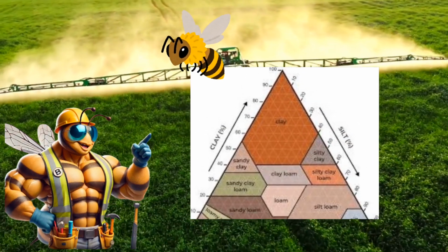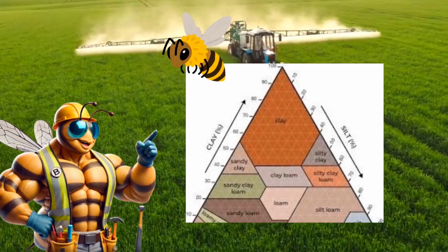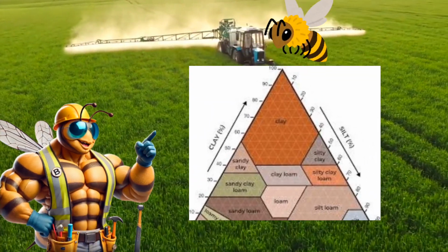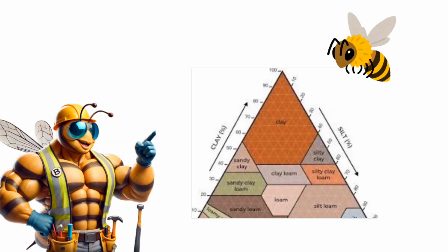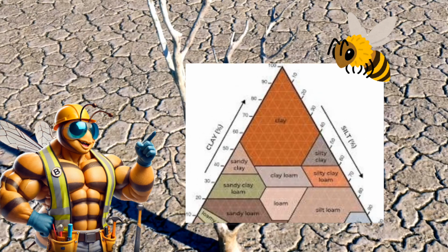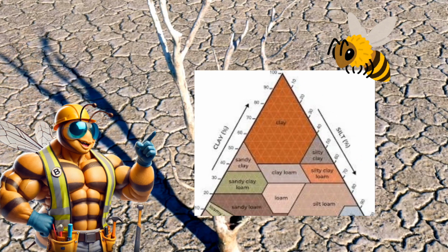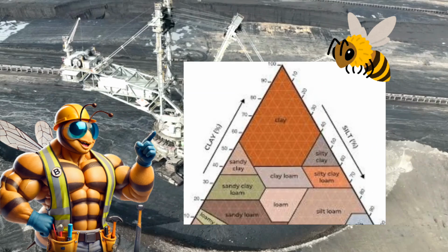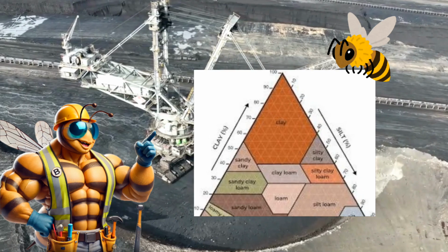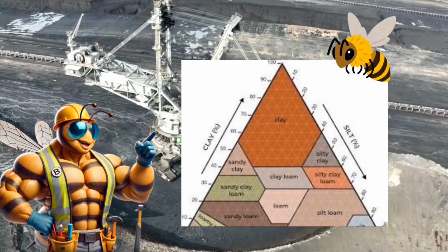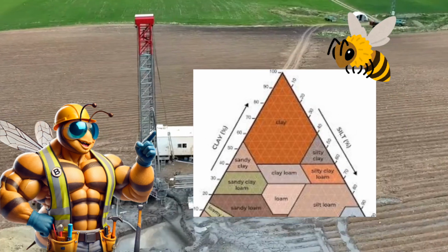To sum it up, the type of soil you're building on has a massive impact on your foundation design. Whether you're dealing with expansive clay, well-drained sand, or troublesome peat, understanding the properties of the soil can save you from a world of trouble down the road. And remember, whether you're a DIY enthusiast or a construction pro, always consult with a geotechnical engineer and refer to the building codes, like the International Building Code, IBC, or the British Standard BS 8004, which provide guidelines for safe foundation design based on soil conditions.